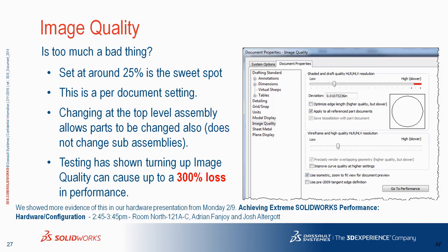I think it was 2006 or 7, something like that, where they made the change. Their image quality was jacked up to the other side of this by default, and if you had your template set up back then and haven't adjusted this setting since, all your parts are being built with this already set too high.